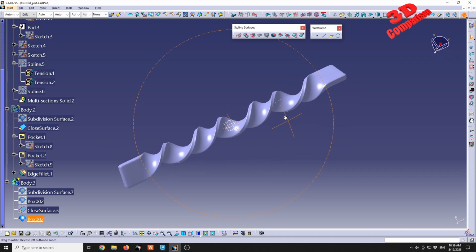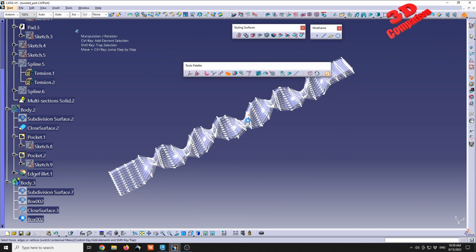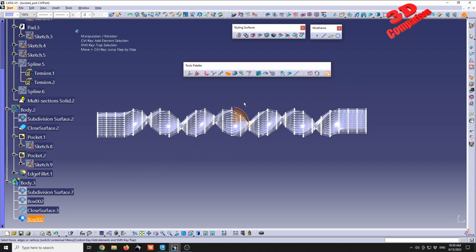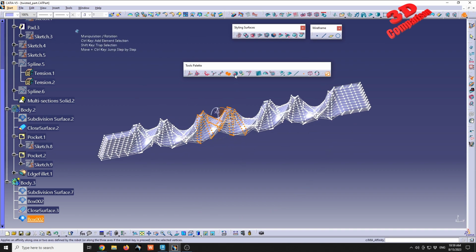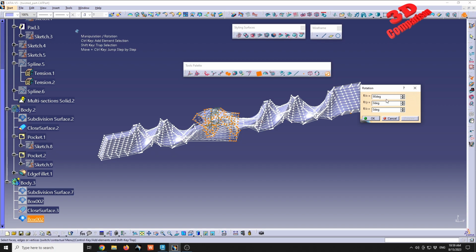So we see we still have that twisted part, and we can further select and rotate elements if you want to do that. But I highly recommend that you do the, let's say, most important rotation and twisting directly in 3ds Max, and you control it over there a little bit better.